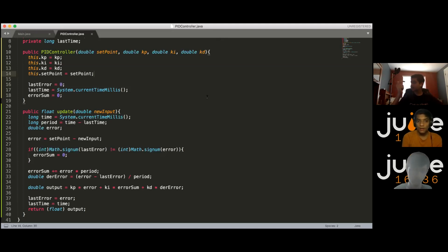And if you're asking, tuning wise, if the integral portion should be more important or more powerful, I would say that's normally not a good idea, because the integral term is used to just fix your overshooting issue a bit. What would happen is, if the integral portion was the main driving portion of PID, your robot would move very slowly at the start because it's still building up, and then it would quickly jump up and exponentially increase its speed until it's crossed the target. And that would cause a great deal of overshooting and wouldn't be as accurate.